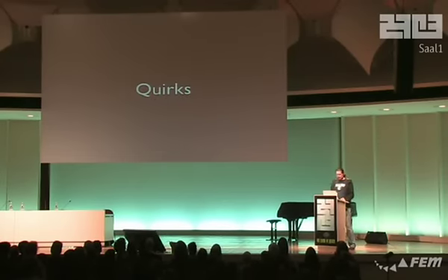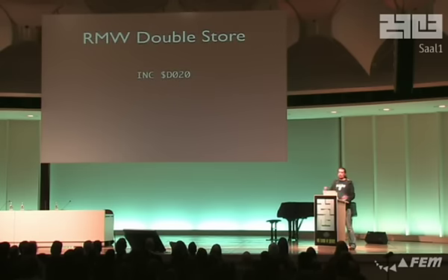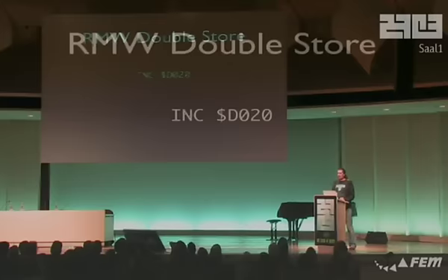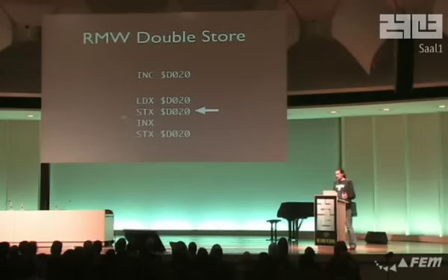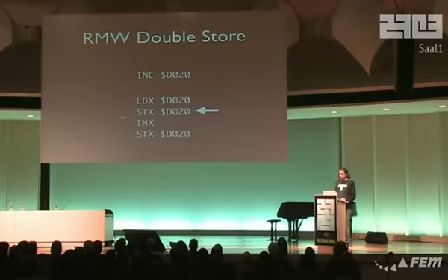So the 6502 has some weird things about it. Some you could consider bugs, some just, well, you don't care, but why do they happen? For example, if you increment something in memory, what you would expect is you read it, you write it. But what happens is it reads it, it writes back the original value, sometimes within those 4 cycles, or 6 cycles, and then it stores the new value. So from a software perspective, you cannot see the difference. But from a hardware perspective, you can measure that. And you can build a computer around that, and you can make use of that oddity and build your copy protections or obfuscation around things like this.